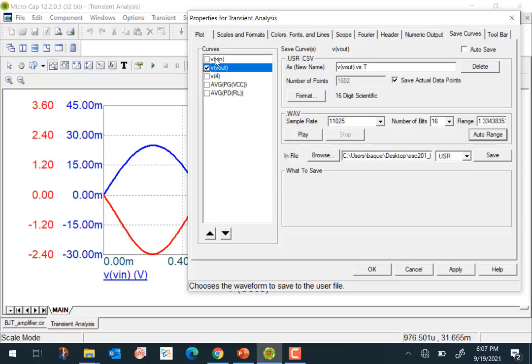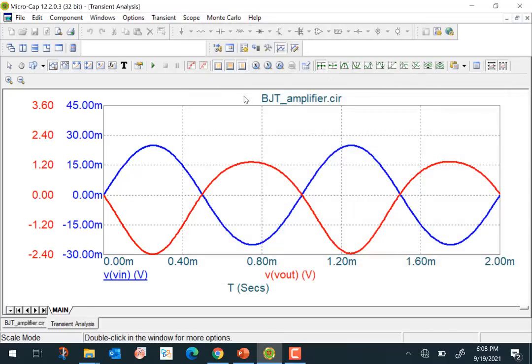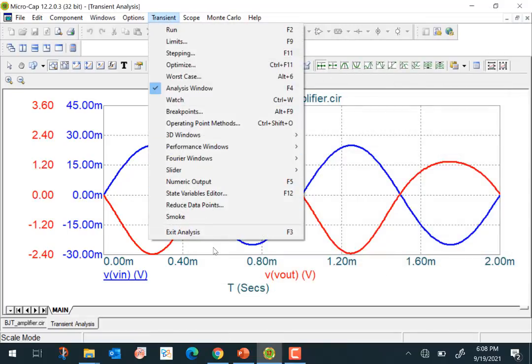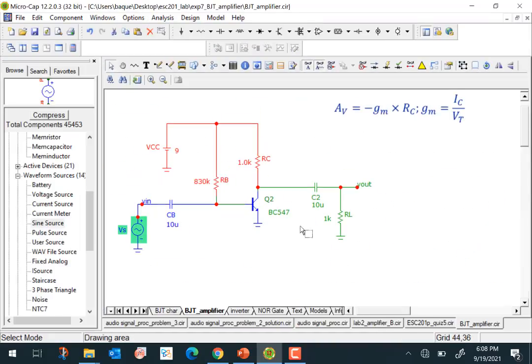And distortion results in that, in addition to the 1 kilohertz input that you gave, when a signal becomes nonlinear, you have other harmonics also. If you listen carefully, you can hear and see that the other harmonics are also present in the output here. So the simulator allows you to explore how an amplifier behaves, and I would suggest you use this to understand all aspects of the amplifier better.